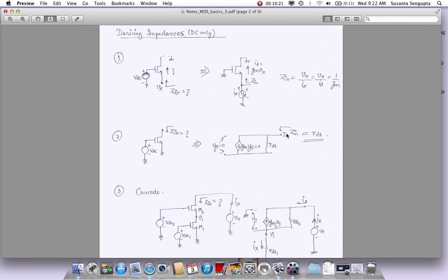And so this is a case where a MOSFET does not have any gate to source. It only has a low frequency signal applied at the drain, and that impedance looking down then will be simply RDS. Okay, so this is another simple example. I'm trying to show you little pieces here which you can get yourself familiarized with, because later on when we build big circuits, all these concepts will be used there.